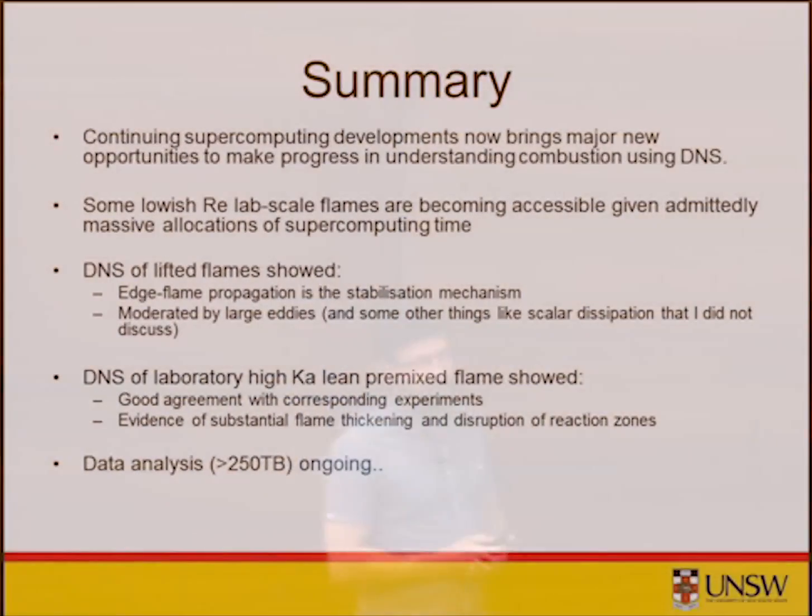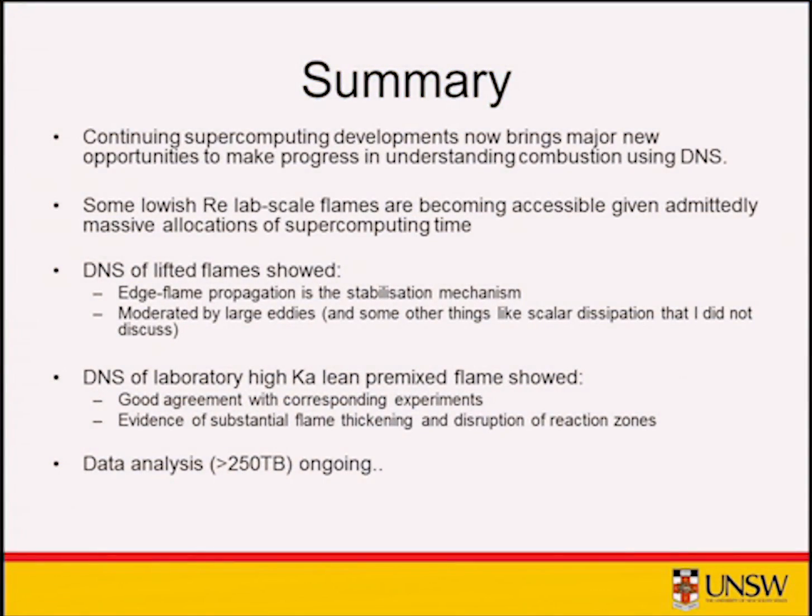three-dimensional. Okay, so in summary, we're in an era now where supercomputers are powerful enough, given really massive allocations of computing time, and I've got to caveat that not everyone has access to those, that we're able to do some lab-scale flames. I've given two examples. For the lifted flames, we're showing that edge flame propagation is the stabilisation mechanism, but this appears to be moderated by the passage of large eddies.